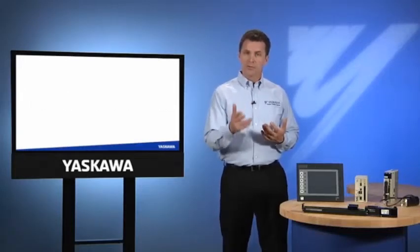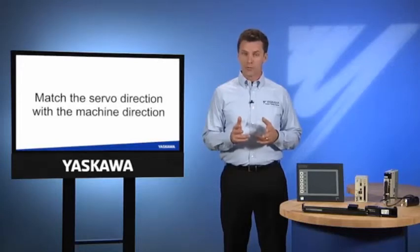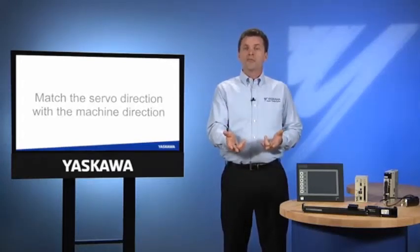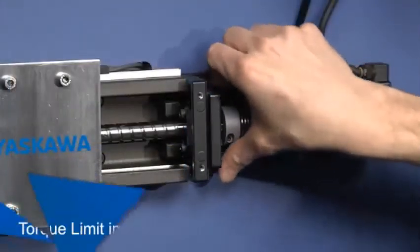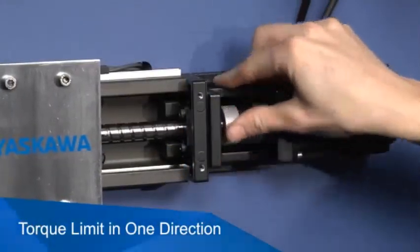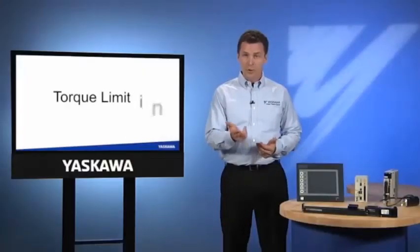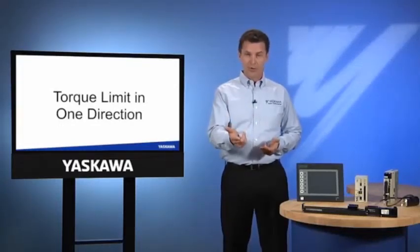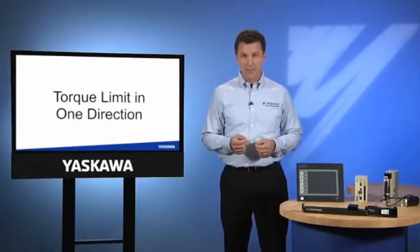It is important to match the servo direction with the machine direction, not only for programming the controller, but also for any other features in the servo amplifier that are sensitive to direction. For example, the servo may use a protective torque limit in one direction, but not in the other. I can manually overpower the motor in one direction, but I can't overpower it in the other direction. So you can see why it's important to understand which direction is forward and which direction is reverse. In some circumstances, this could create catastrophic damage to your machine if not properly configured.